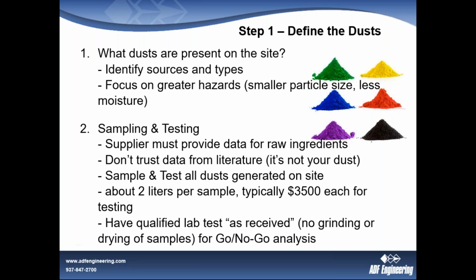What I generally recommend that you do is test your dust. Okay, don't rely on literature to tell you what the explosion hazards of your dust are, because whoever put that data together in the literature isn't familiar with your dust. Okay, particularly if you are processing, grinding, drying, doing any of these things with your material, it is different than what is in literature.